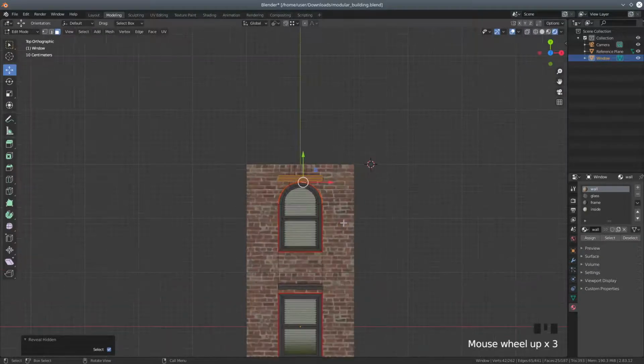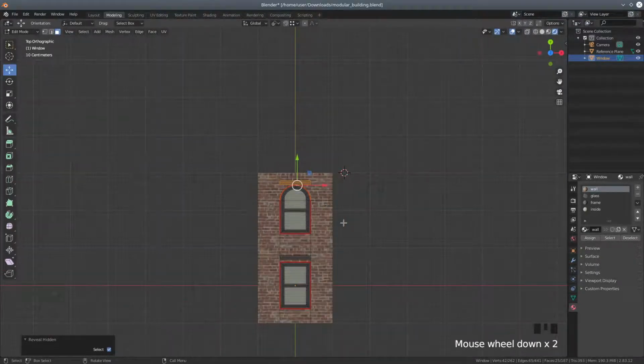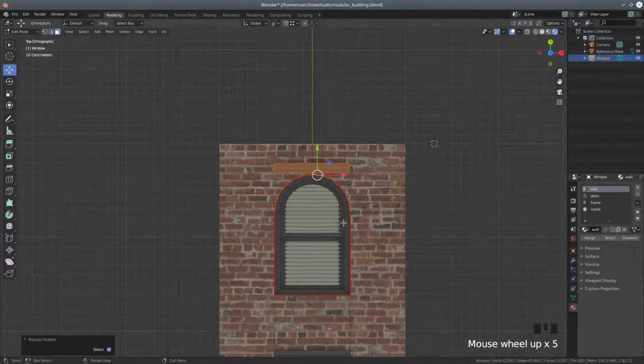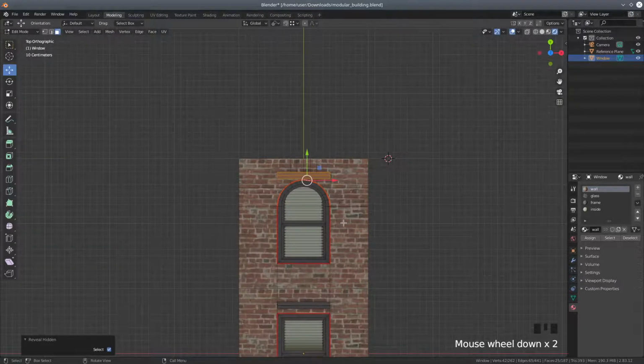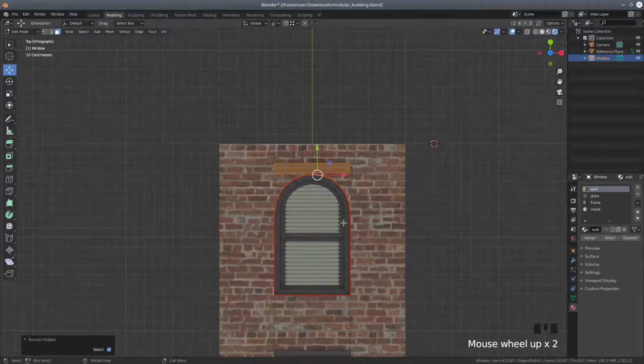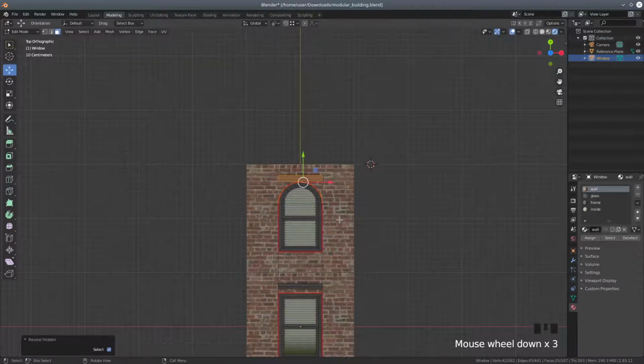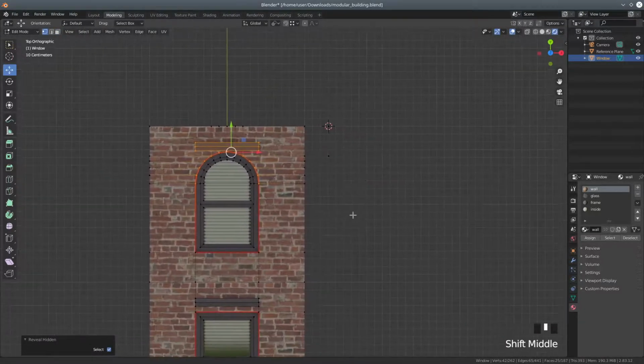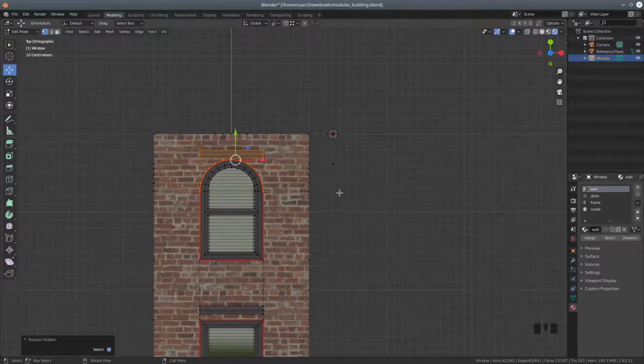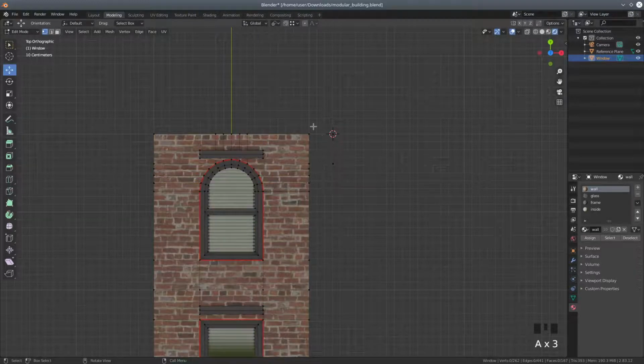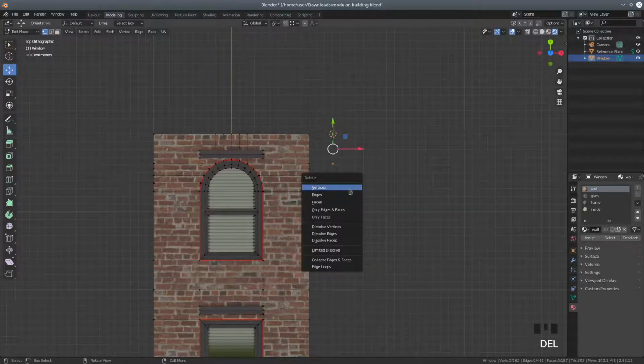do you know, if I didn't know better, I would say that that window is still a bit out of shape. But let's not worry about it. I think we still need to reduce the size of that window down. Okay, we'll have a look at that in a minute. Or we could have a look at it now. Let's delete some of these vertices that we don't need. So just select everything with A a few times, B for box select, select those, press delete, delete vertices.